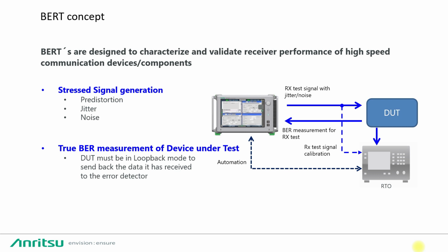What's the purpose of predistortion? In order to compensate for high-frequency signal losses on communication links, many technologies are using predistortion techniques called pre-emphasis, de-emphasis, and pre-shoot at the transmitter. High-frequency parts of the signal around bit transitions are amplified because they are mostly affected by the link's bandwidth limitation and therefore attenuated. PCI Express and USB define certain setups of de-emphasis and pre-shoots, which are called presets. I'll show and discuss them later during the demo.